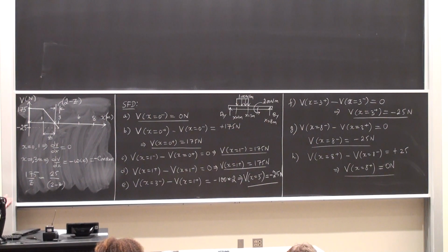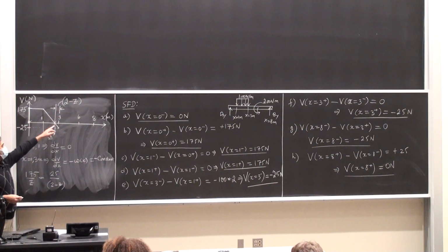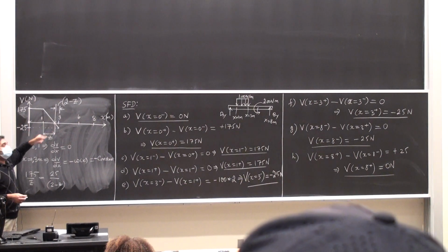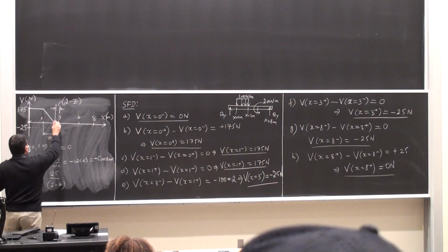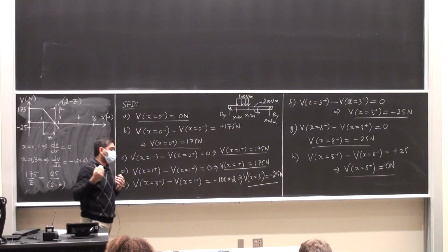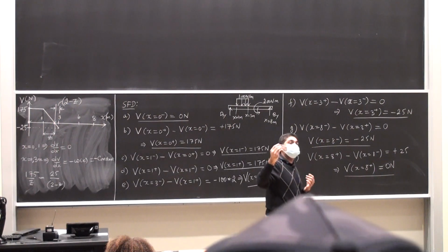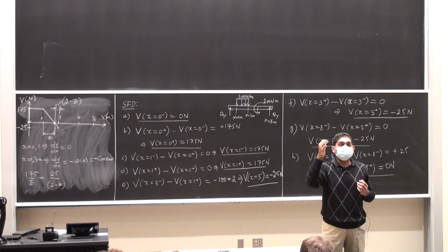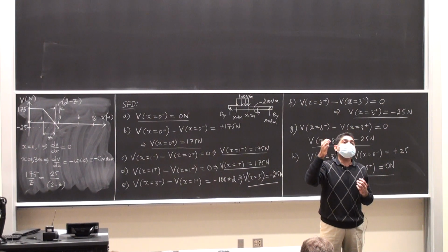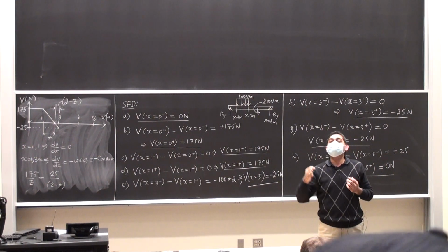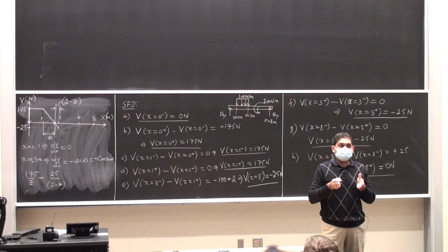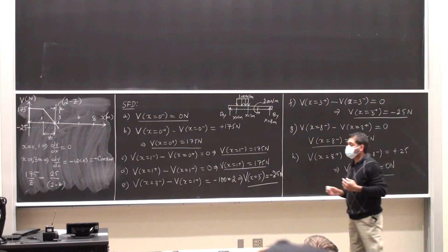Here is what I'm trying to do. The shear force is crossing the x-axis and going on to the negative side. That point there is a point of great interest for me because we know in the back of our mind that the slope of the bending moment diagram is equal to the shear force value. So which means the slope of the bending moment diagram at that point is equal to 0. If the slope of a curve is 0, then it means the curve is either hitting a maximum or a minimum. So I want to find out what exactly that location of crossover is. Okay, so that's called the point of zero crossing.